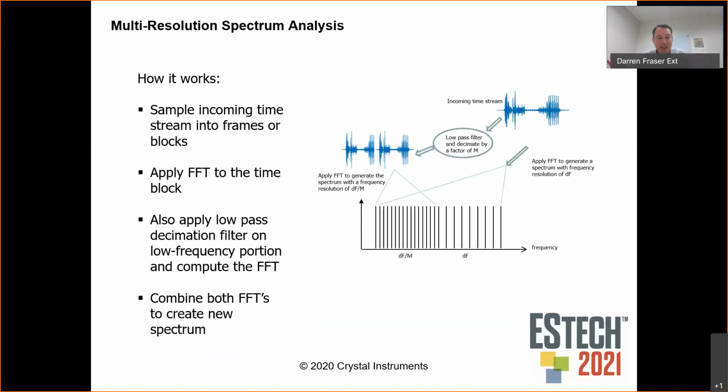Well, with that decimation filter applied and then the FFT taken, we have to choose, of course, a frequency somewhere in the midpoint, a mid-span cutoff frequency. And when we do that, we can get a better resolution FFT because we've decimated that frame. So we can get a better resolution FFT down at the halfway point of that spectrum.